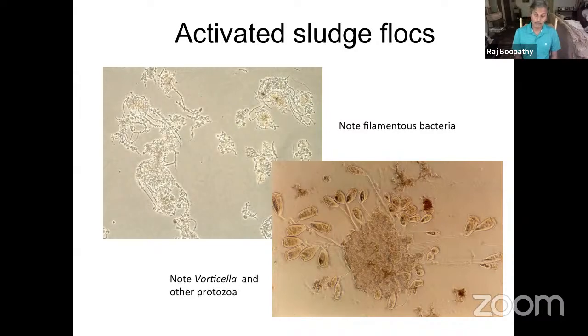But the one organism that does the bulk of the removal in the sewage is called Zoogloea ramigera, which is the organism we prefer. They remove the bulk of the carbon in the system. And sometimes there is a shock in the system because the wastewater is coming from different households, and sometimes people put toxic material in the system, and you're going to kill a bunch of these organisms. So in that case, a succession of microbes takes place. You're going to wipe out the good ones because they are sensitive to this toxic chemical.